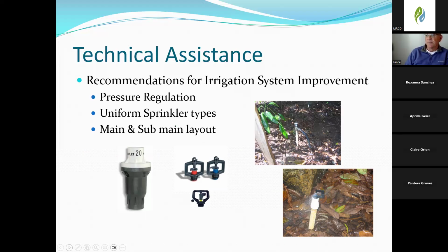And they had 9 irrigation blocks. We redesigned the system. We put in a 3-inch main from the meter all the way to the top of the hill. Then installed the laterals coming back down, and off of that 3-inch with 1-inch laterals, and we got from 9 irrigation blocks, we ended up with 3. So we need to make sure that we maintain as big a pipe going up a hill as we can.